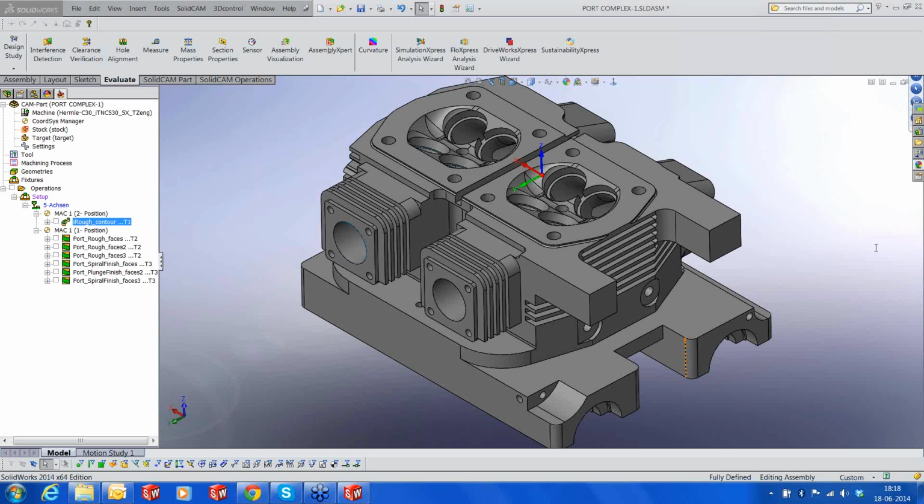Can we finish this in 3-axis? Honestly, we can finish in 3-axis, but it's going to take much more time, much more effort, which is actually not worth it, because you're going to run into several calculations. The first thing you need to decide is which is going to be your best orientation to orient yourself and then do the 3-axis finishing. So getting to that orientation itself is going to be a major headache.